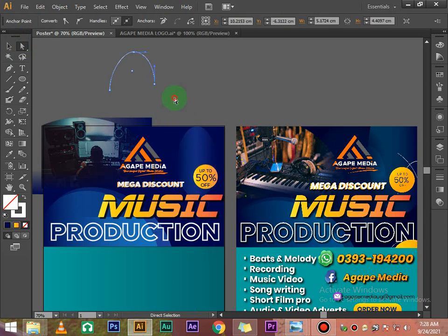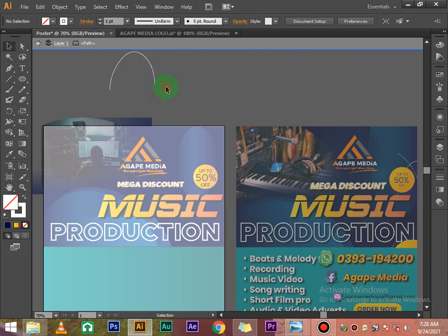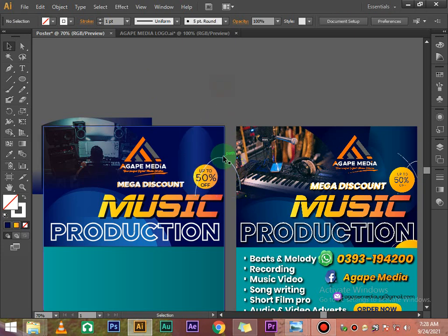Sorry, that wasn't supposed to happen. I will just select it and drag it. Okay, I'm just going to drag it and have it somewhere here, like that. Now you realize it's supposed to be behind that, so I will just use the shortcut for arranging: Control plus the open bracket. Since we are sending it behind, it should be the open bracket, so I'll just keep on clicking until it goes behind that, like that.